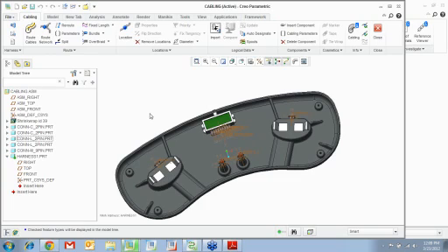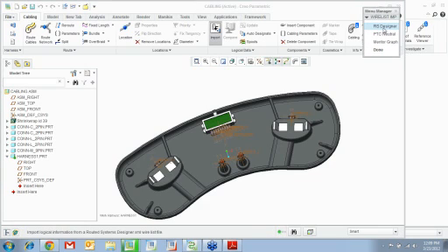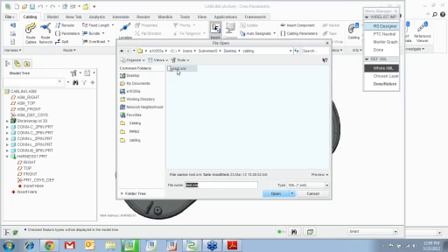Now, first thing we're going to do is import this XML file. How do we import this? You have this icon right here. Click on that. You're going to say RS Designer, which is Routed Systems Designer. This is what it used to be called earlier. You want to import a whole XML or just a part of it. I'm just going to import the whole XML. I'm going to browse and pick that test XML.